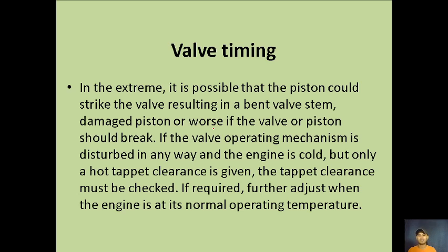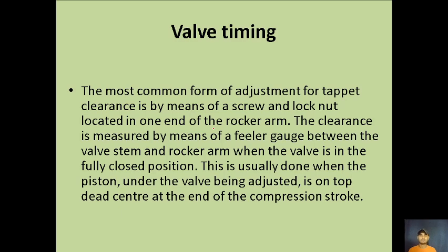If the valve operating mechanism is disturbed in any way and the engine is cold, but only a hot tappet clearance is given, the tappet clearance must be checked, and if required, further adjusted when the engine is at its normal operating temperature. So always check your manual for the correct temperature for doing this valve timing or tappet clearance.